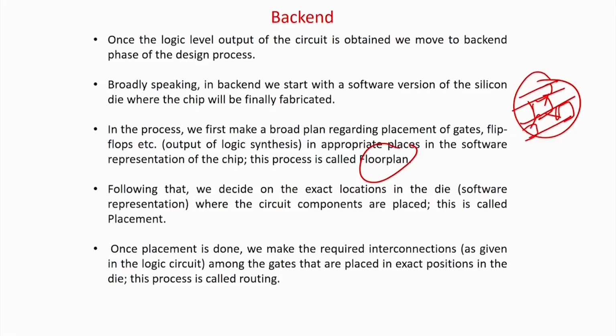So now again tell me what are the optimizations over here. Simple, I require a very compact design because if I have a very large design things may get cluttered up and you will obviously get an implementation but it will be high cost. So I want to put everything together, but it should not be so compressed that I cannot put everything. So I have to get an optimal size die. And of course, the optimality cannot be coming in years. So I have to have a very fast algorithm so that I can get a good quality back-end design in a reasonable amount of time.